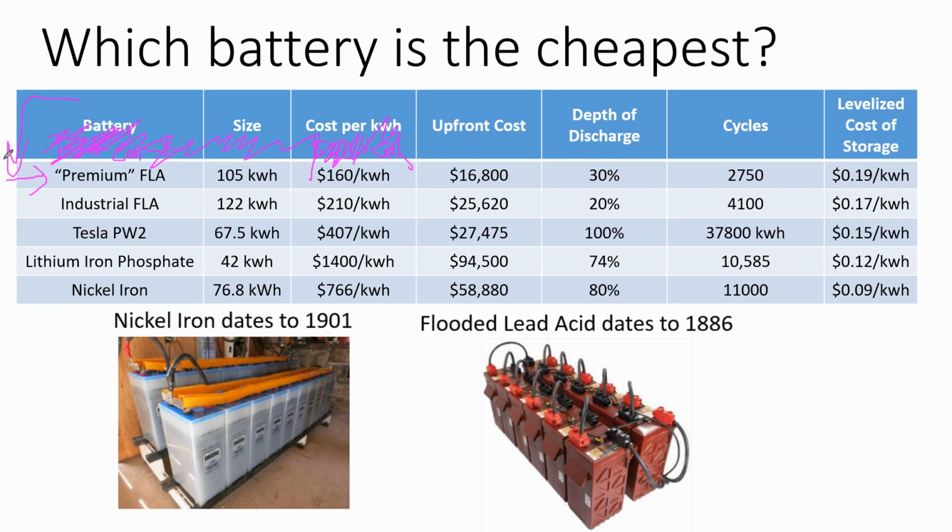And I said, well, why do you do that? And he says, well, I really do tiny house off-grid systems. And what I find is that A, my customers can't afford the more expensive batteries. B, these industrial sized flooded lead acid are so heavy that just transporting them to the job site becomes an issue. Whereas golf cart batteries, you might have to do a lot of wiring, and you might take a couple of trips out to the job site to get all the batteries there, but you can actually pick them up and move them. So there are some logistical issues.